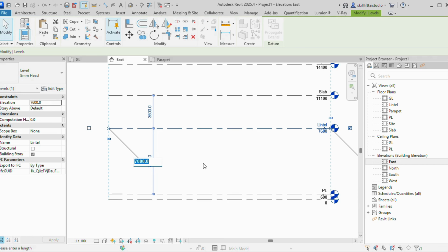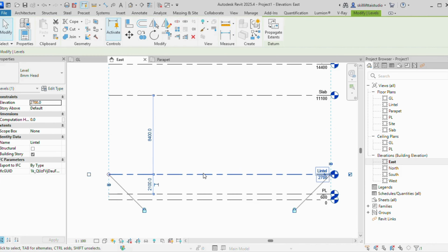The best part of Revit is that we need not convert our measurements or dimensions. If this is in mm, as we can see, these are in millimeters. If I have to give dimensions, instead of 2100, I'll just type 2.1 meters. If I use the SI unit, it automatically converts it into mm. This need not be in metric only.